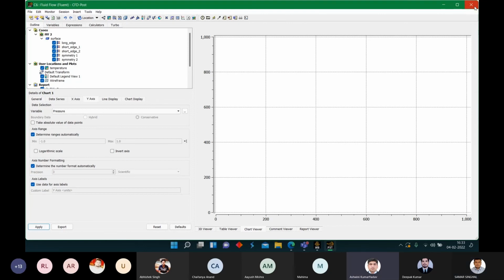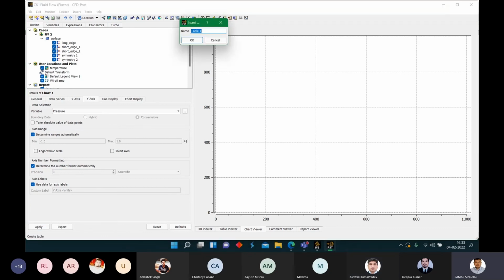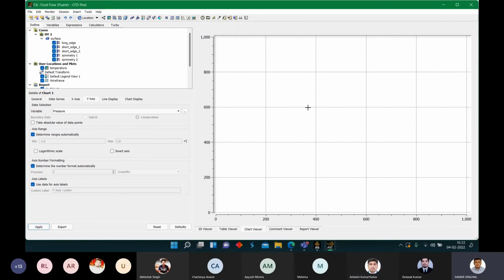The temperature profile has been generated. Now anyone can do post processing and plot the graph, whatever they want. You can also switch to tabular values in the table, and then you can compare with your code. You can import those values into MATLAB or other software. Then you can plot both graphs and see the difference and check your code.